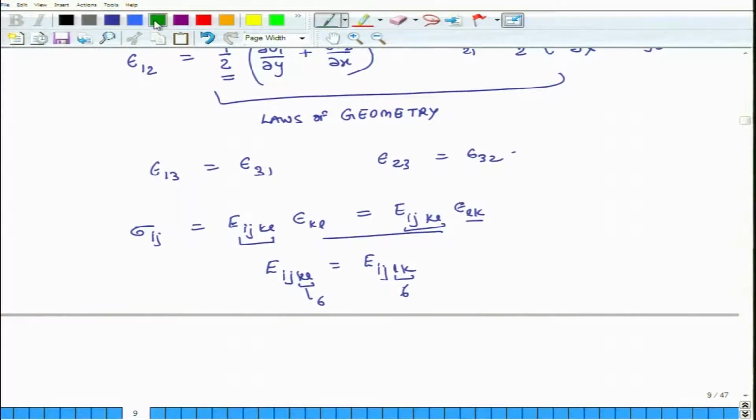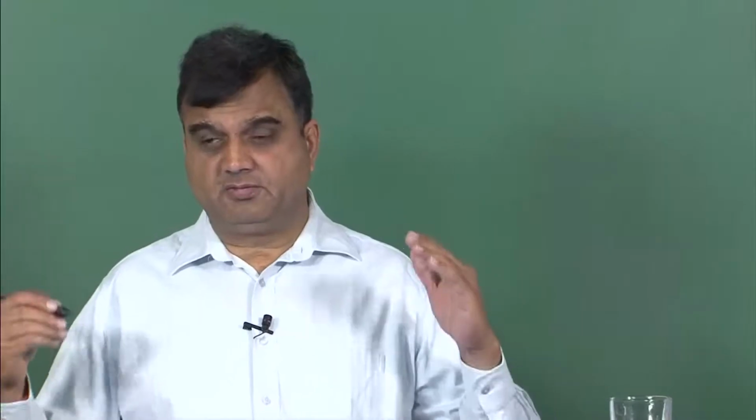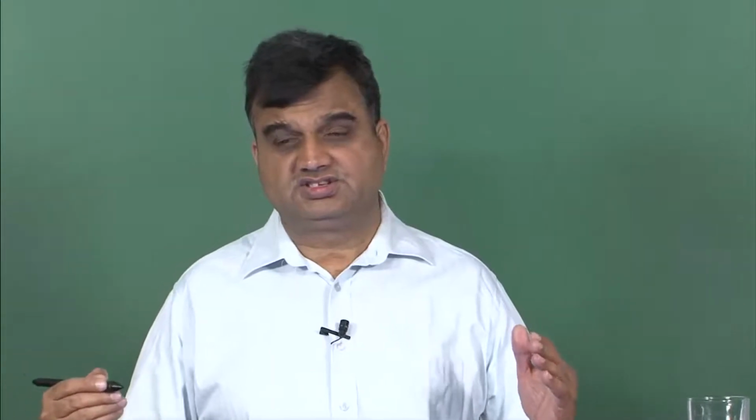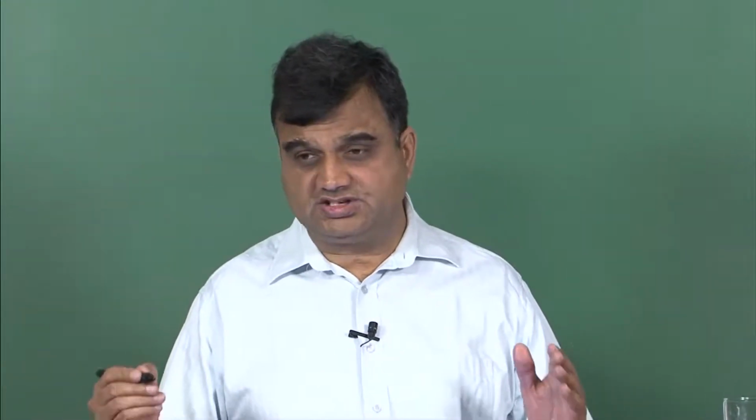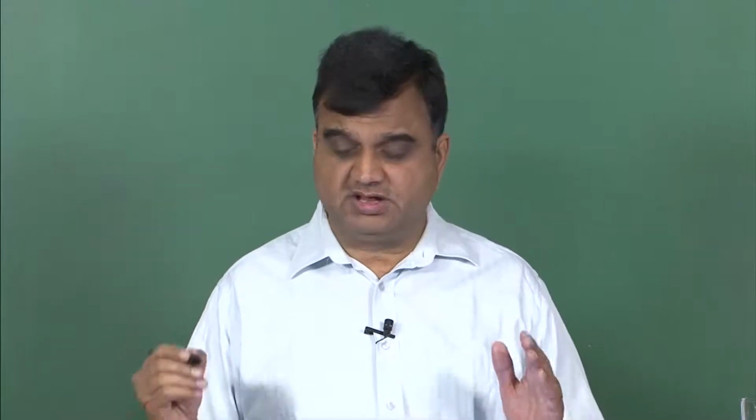And in our original discussion, because of stress symmetry, these have 6 different possible configurations. Because of strain symmetry, these have 6 combinations. So, the number of constants goes down from 81 to 54 to 36. Instead of having 9 equations, we now have 6 equations involving 6 stresses, 6 strains and a stiffness tensor of dimensions 6 by 6.